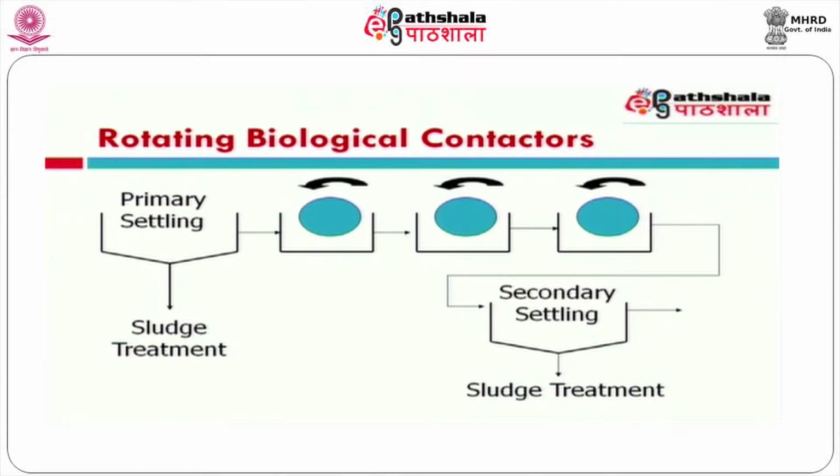So, if you want to implement this technology in a wastewater treatment facility, we have to provide primary settling facility followed by the biological reactor. In some cases primary treatment is not required. If the suspended solids are more, in that situation only we can incorporate primary settling. Normally that primary settling can be avoided for an extended aeration system. For rotating biological contactors, in order to minimize the load entering into the secondary treatment facility, definitely we can have a primary settler.